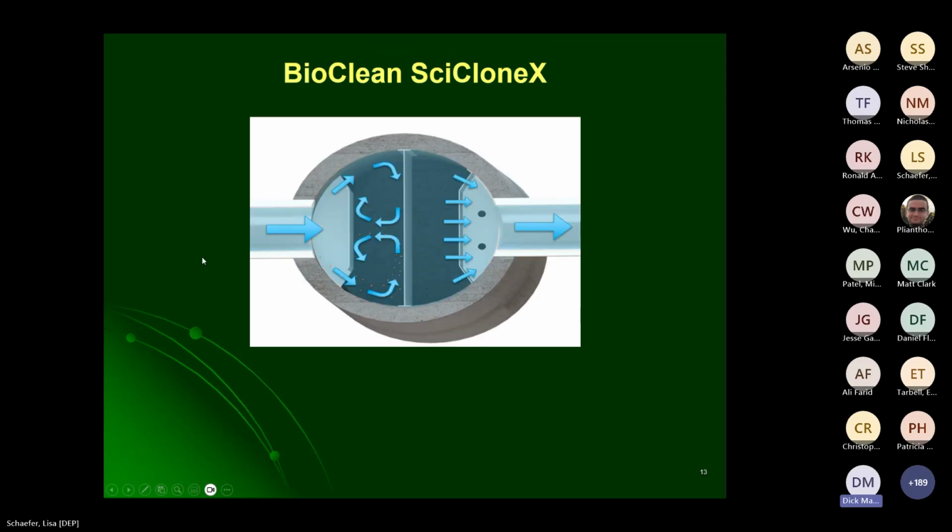It comes in, you see how it gets split in the front there. It then develops a vortex motion, which basically retains the stormwater for a longer period of time, enhancing the settlement out, and then goes to the outlet pipe, and it goes through the outlet thing like that. Again, inlet and outlet must be aligned on 180 degrees, or it's not going to work. Next slide.